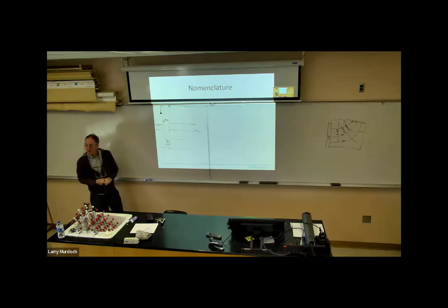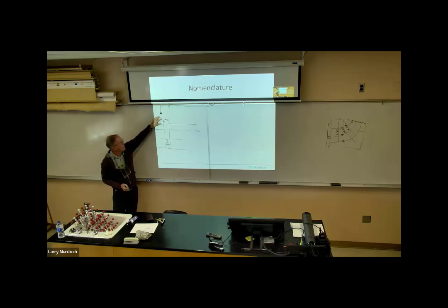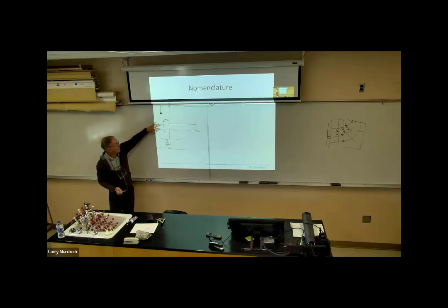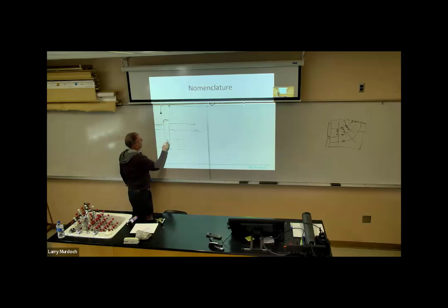It's not always done that way. If the water table is shallow, then you can put a pump up here and lift the water up to the ground surface just by suction, like you lift water with a straw out of a drink. If you're deeper than about 15 feet, though, that's not going to work, and you need a pump down here to push the water up. So we've got a pump down here, and start pumping, and pump the water out at a flow rate Q.